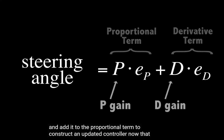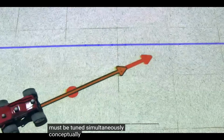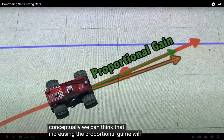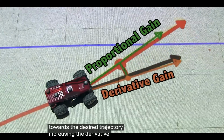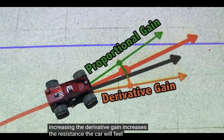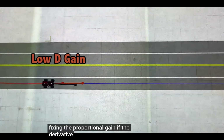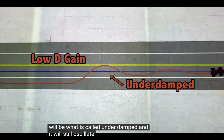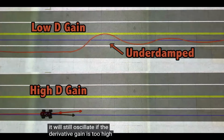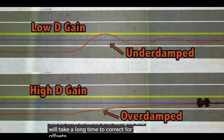updated controller. Now that we have two terms, we have two gains that must be tuned simultaneously. Conceptually, we can think that increasing the proportional gain will increase the pull that the vehicle feels towards the desired trajectory. Increasing the derivative gain increases the resistance the car will feel against moving too quickly towards the line. Fixing the proportional gain, if the derivative gain is too low, the system will be what is called underdamped and it will still oscillate. If the derivative gain is too high, the system will be what is called overdamped and will take a long time to correct for offsets.